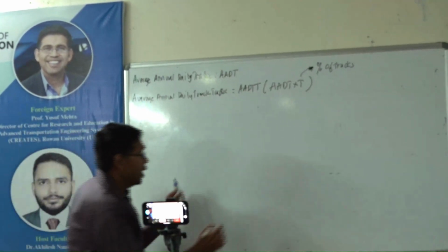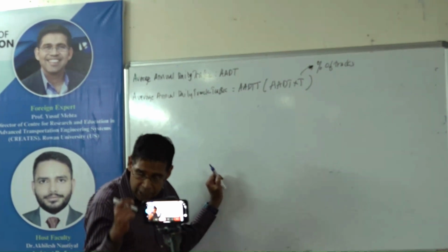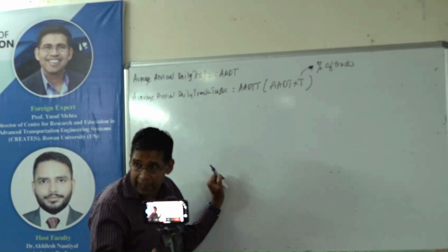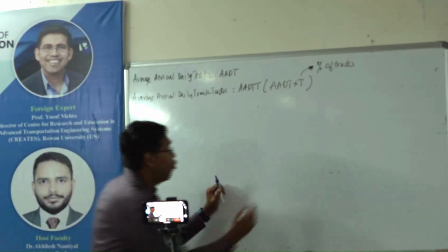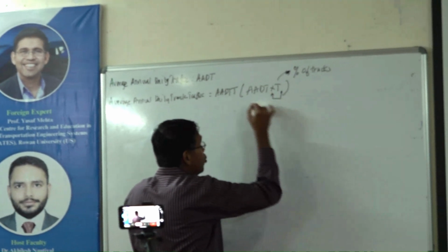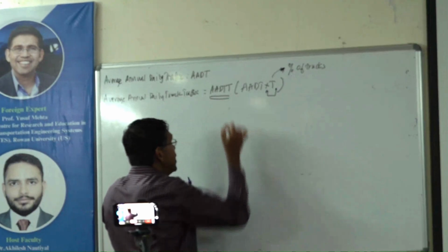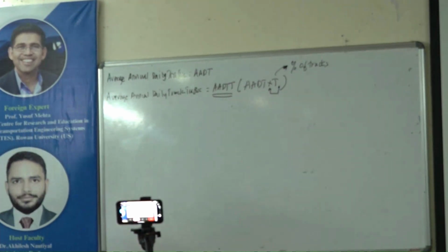In pavement design, as I just explained to you, if the load is too small, it has no impact on the damage. A bicycle going on a highway will cause no damage. So we are only focused on this number eventually. You need to get AADTT, because that's all you care about, since that's what causes damage on the pavement.